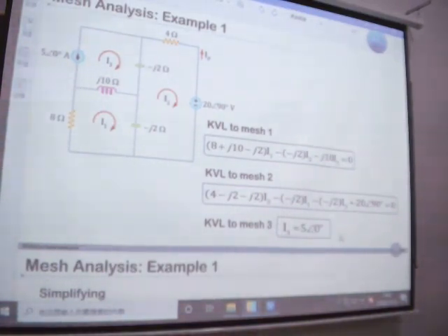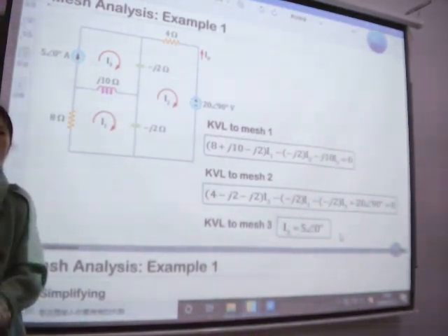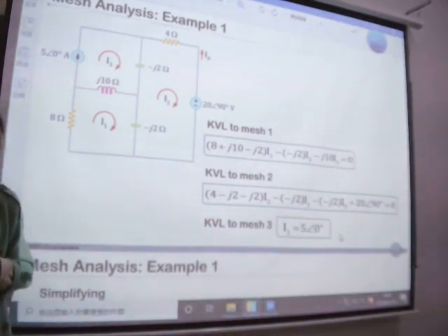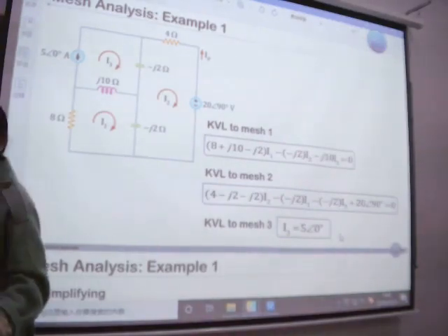If we have some current source inside and we still want to use the shortcut way, it's okay, but it seems more difficult, right? We can use the traditional KVL analysis. It might be better. This circuit just has 3 loops, but if you have 300, I think it still might be better.